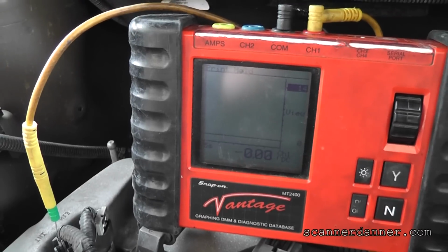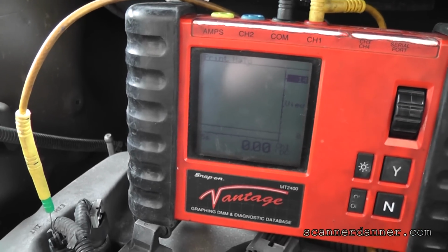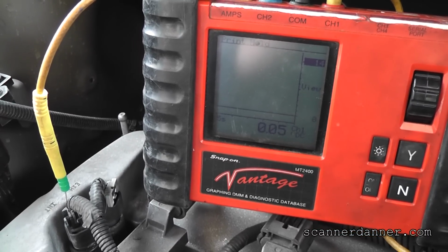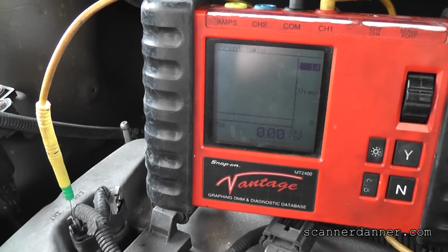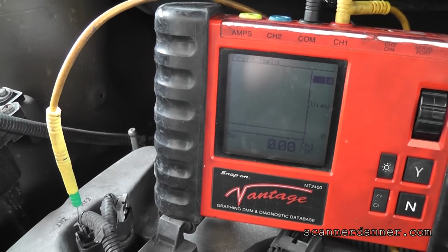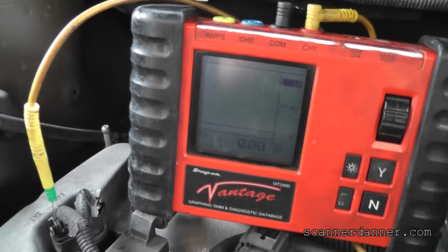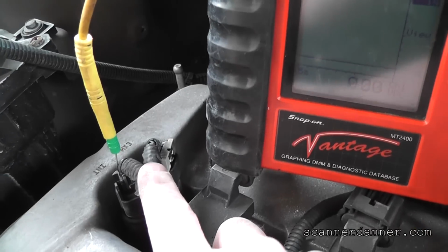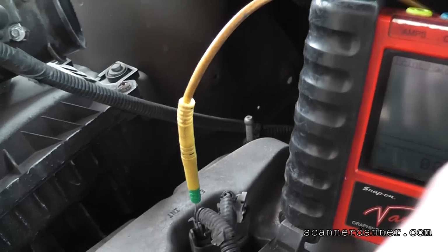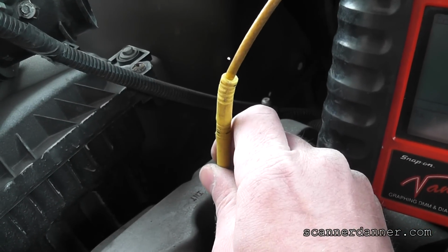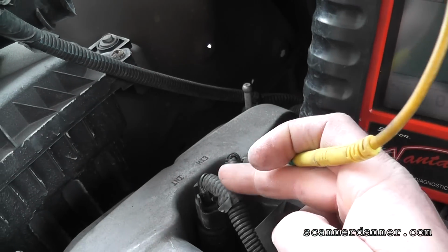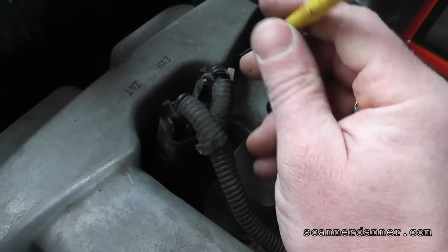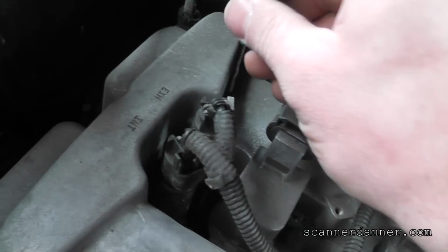What we're going to do is a ground-to-ground voltage drop test with the circuit energized. Turn the circuit on. You see a little voltage rise there. That's good. We want to see that. So that's how you check it, bi-directionally. That's a good ground right there. That is a good control. We definitely don't need to be jumping wires together like the manufacturer flowchart has us do. That bias voltage, I think, was key for this. You saw on this positive wire that 0.9 of a volt signal. Let me get you back on the exhaust side.